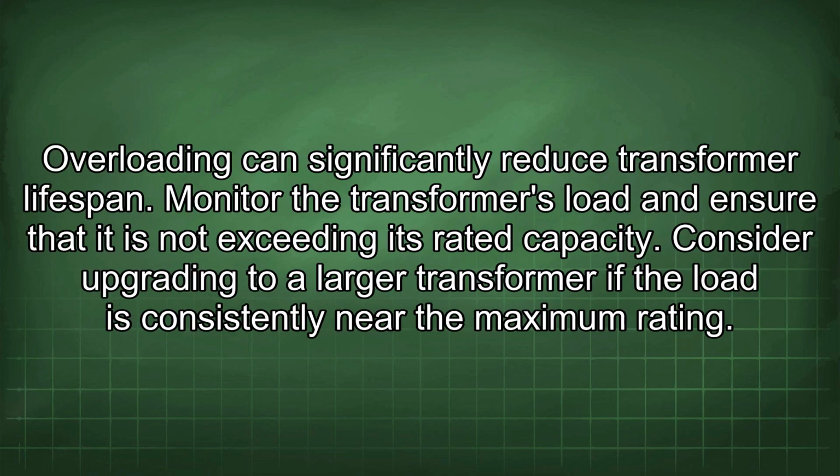Overloading can significantly reduce transformer lifespan. Monitor the transformer's load and ensure that it is not exceeding its rated capacity. Consider upgrading to a larger transformer if the load is consistently near the maximum rating.